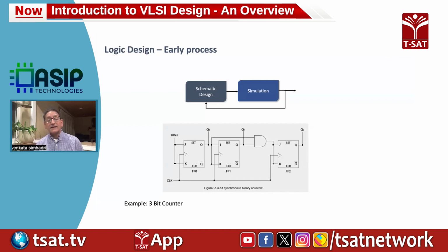And then you extract a netlist out of it, and you simulate it in SPICE. That used to be the most popular simulation tool in those days. And we still use SPICE for analog design, but in those days most of the digital circuits also were done in SPICE. And then you simulate it until you reach the performance you want, and then you release that to the layout.